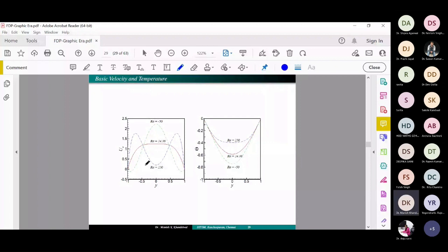That is one of the predictions that instabilities are available in the flow, but it's not mandatory, because this statement is generally useful for inviscid theory. But in viscous fluid also, we can see this type of inflection points in the basic flow. That inflection point will give an instability in the flow.